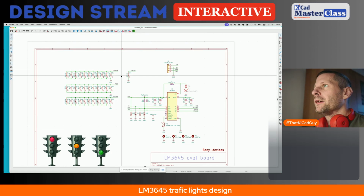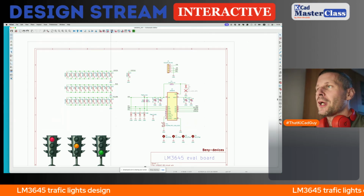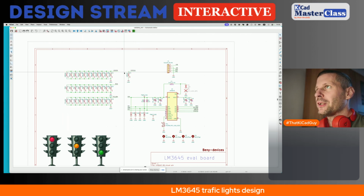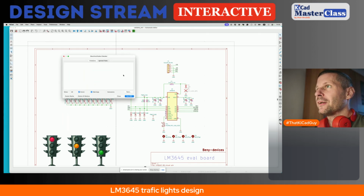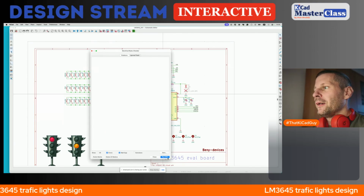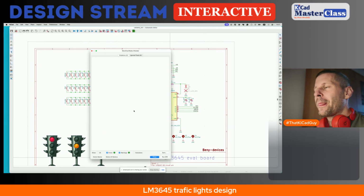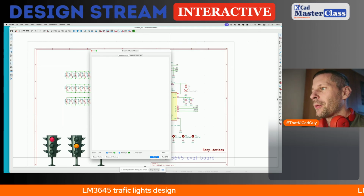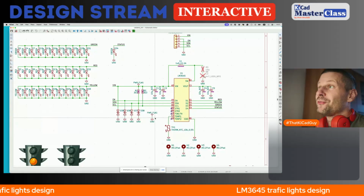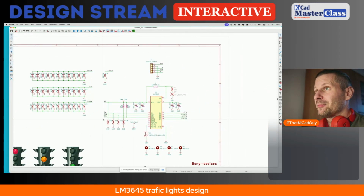So let's make a quick check. Annotation, okay, we have a completely annotated schematic. Let's go ERC, electric rule check. If there are some 0, 0, so we did a good job last time. No ERC findings. Frankly, there is nothing complex in the schematic.